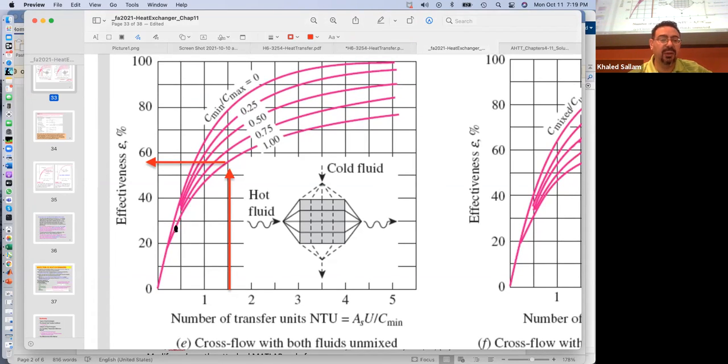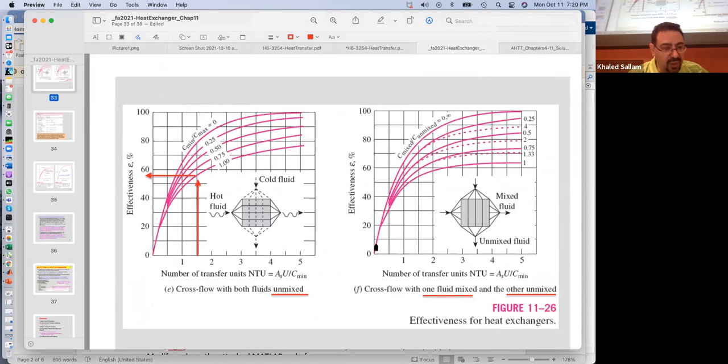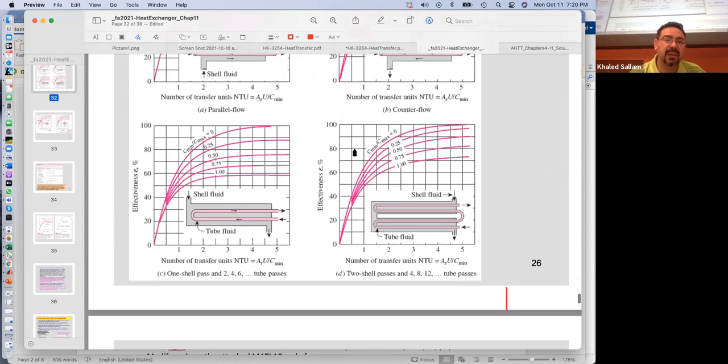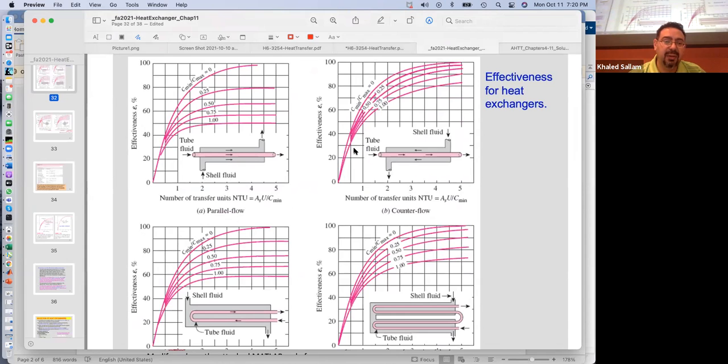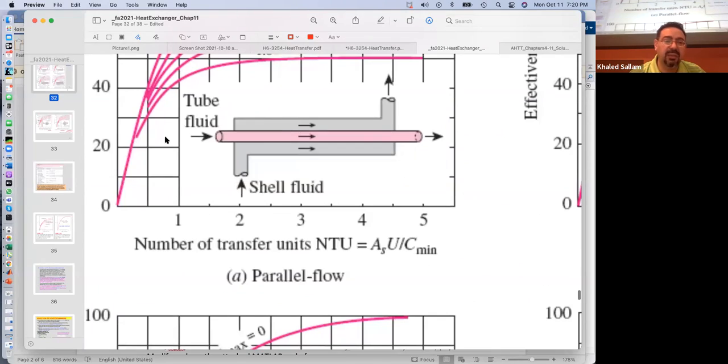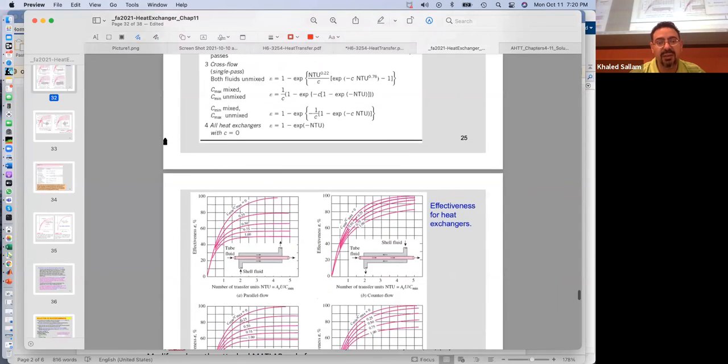No, it's just that if you continue, they would have painted this red. They get so close together, they are just really red, right? And practically speaking, why would you use a heat exchanger that has 50% effectiveness? That sucks, basically. This would be a really tiny heat exchanger. So no, all of them could have gone all the way to 1. All the equations should go to 1. It's just that they get so close there is no point in painting them. Even this one, look at this. You just stop it here because you would need more or less exactly the same curve.